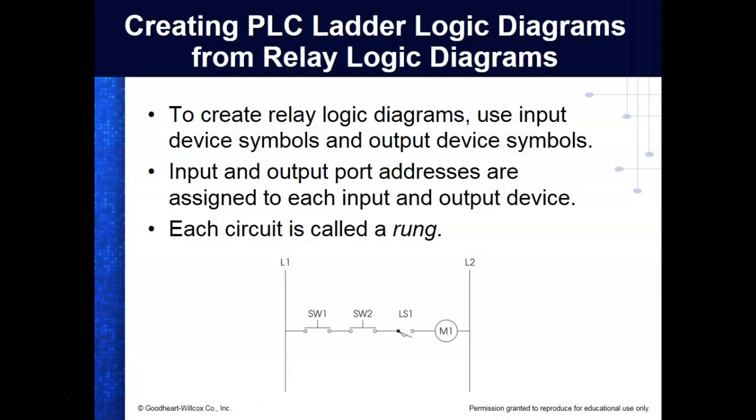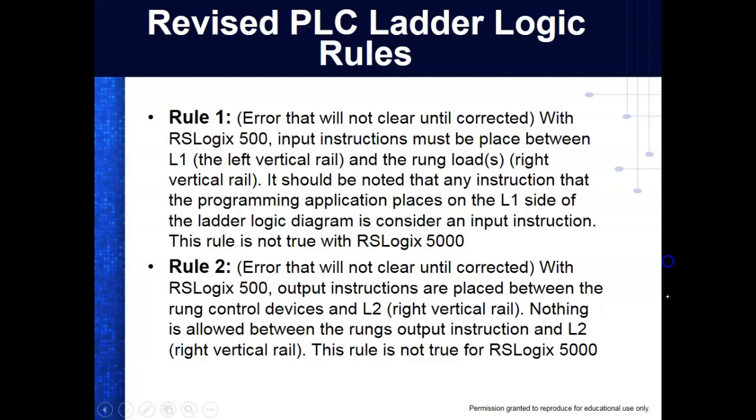So to create a relay logic program, of course, this is a very simple relay logic program. We're using two normally open push buttons, even though they've got the symbol. I don't like to draw normally open push buttons that way, so that's the symbol for what we call a spring-loaded push button. Y'all understand those? So it should be drawn like this. Then we have a symbol for a normally open limit switch, and then the symbol for a relay coil.